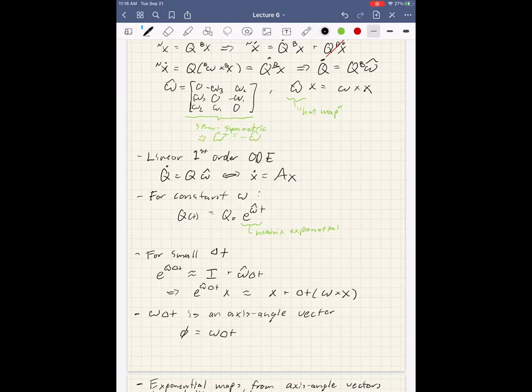And practically, in a strapped-down inertial navigation system with a thing like this, you're sampling at 100 hertz plus, and that's plenty. So it's not really practically an issue hitting the sample rates, most of the time. Decent gyros can sample at hundreds of hertz, kilohertz even, and you're not going to spin faster than that on any real rigid body system. So I don't think the sample rate's typically a problem. Noise and bias and all that other stuff are problems, but that gets dealt with in some kind of Kalman filter or whatever, right? But the core idea ports into the Kalman filter setup pretty cleanly.